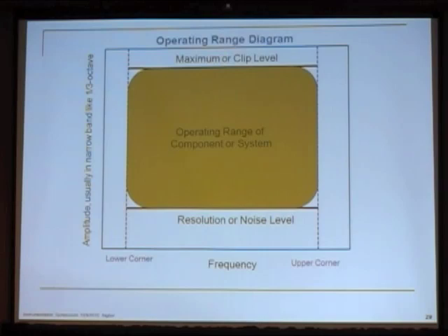Frequency is the x-axis, and amplitude. Amplitude is kind of weird because this is a Fourier spectrum, but Fourier spectra don't work here. So generally you go back to the acoustics arena and you use narrowband RMS or peak values. The third octave, fifth octave, something like that is pretty standard. So it's narrowband, so you can actually compare amplitudes.